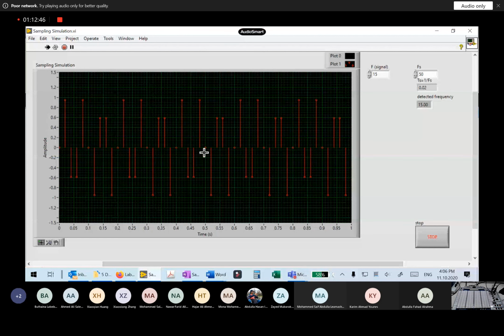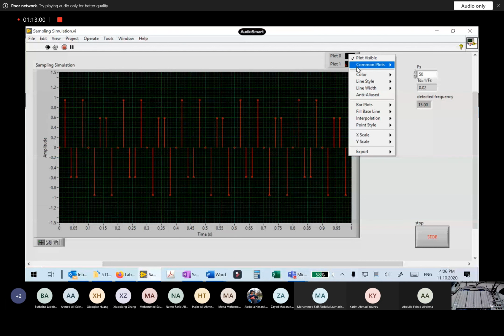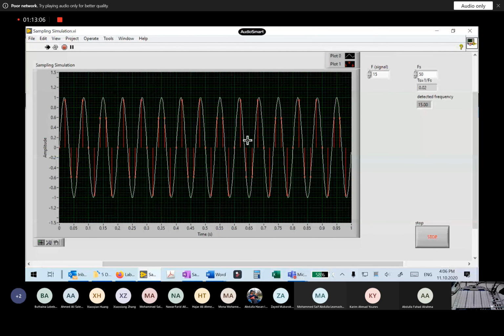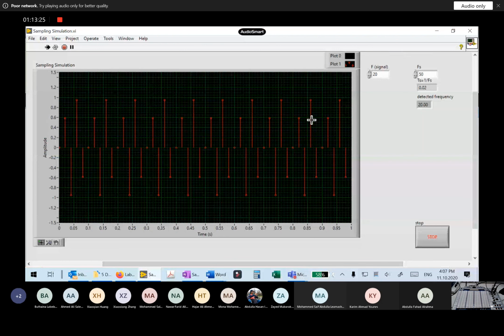can you tell from this shape that this is a sine wave? Clearly, this shape here doesn't look like a sine wave, right? I know the real one, the white one, is a sine wave. But when I hide the real one, the way the computer sees the signal doesn't look like a sine wave. So the higher the frequency, the more the shape will be far from the real one.